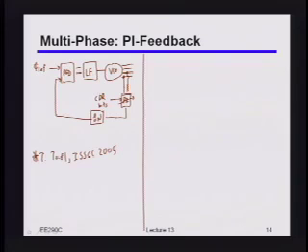Although that has the unfortunate characteristic that, because you're generating these big jumps, you then have to make the PLL sufficiently low bandwidth that it filters those jumps out, right? So you could do that, but unfortunately that has some not so good implications in terms of the PLL loop bandwidth. Yeah, go ahead. Can you alter the transfer function of the phase frequency detector? Ah, okay. Now tell me a little bit more about that. So what exactly are you going to do? Well, first, since you said you want it to be at a lower rate, your updates are coming at f_ref.